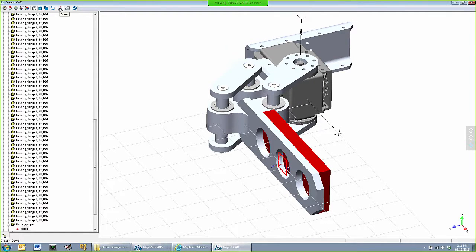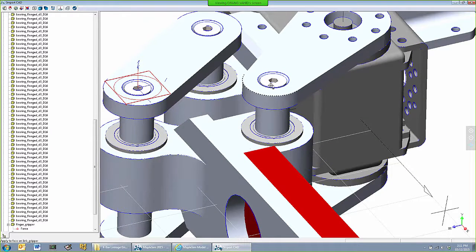So I need to include positions on this CAD object that signify the axis of revolution of each revolute joint. If I add one here, as far as the rigid body is concerned, that's the axis for one of the revolutes. I can add another one to one of the circles on the other side.